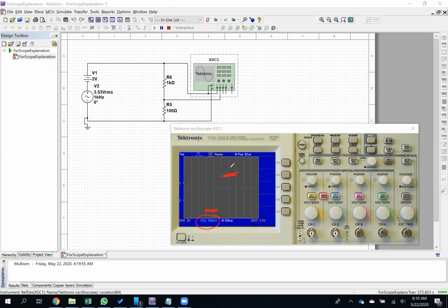Now, to read that a little bit more accurately, I might shift it horizontally so that I can get the peak of that waveform to cross the ticks a little more clearly. Actually, it's easier for me to see there. So there's 5, 3, 4. Oh, this scope has 4 ticks. That is rough. I'm so used to reading 5.